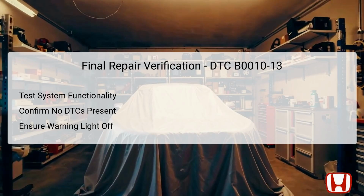If any codes are still in the system, further investigation may be warranted. Finally, confirm the airbag warning light is no longer illuminated. This indicates that the system is back to a normal operating state. Thorough verification ensures peace of mind regarding passenger safety.